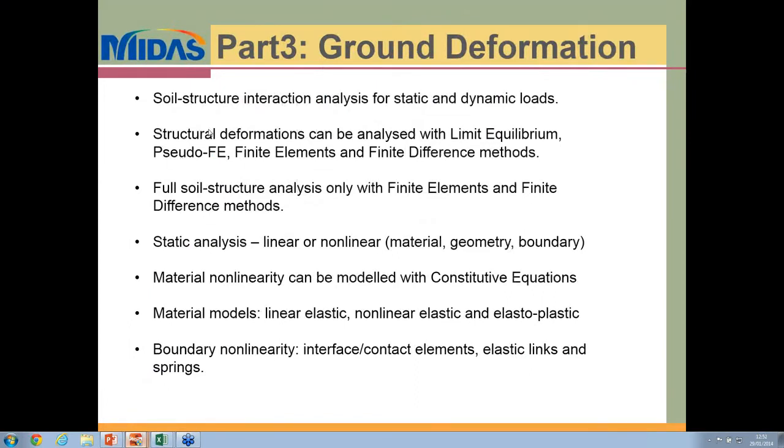Then in the third part, for the ground deformation analysis, the soil structure interaction analysis can be performed for both the static and the dynamic loads. And for analyzing the deformations in the structural members, they can be analyzed either through the limit equilibrium solutions, or you have the pseudo FE solutions, finite elements, and the finite differences.